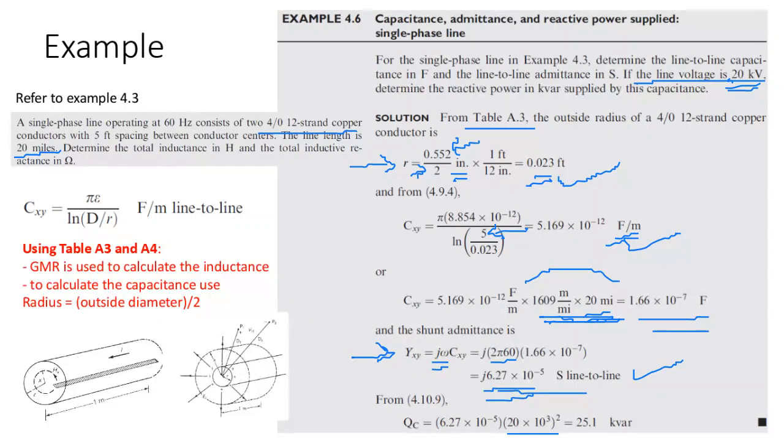Okay, this is a single phase, by the way. It's a single phase, so it's not even 3-phase. If it's a 3-phase, we don't tell you this is a 3-phase. It means line to line. So this is a single phase, so just multiply by square root of line to neutral or line to line. It's a single phase, so not three phase. If it were, it would be a square root of 3. So that is what you will get, kilovar.